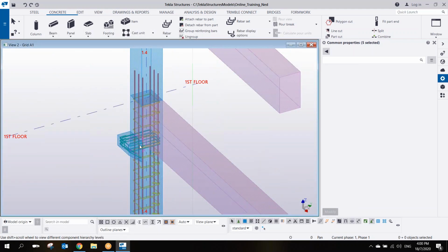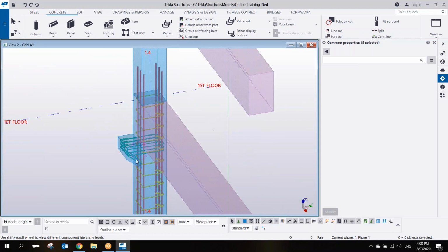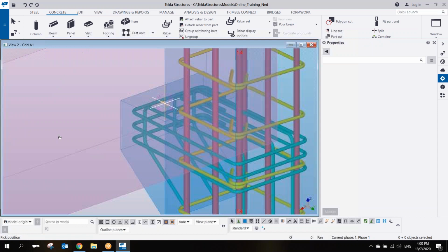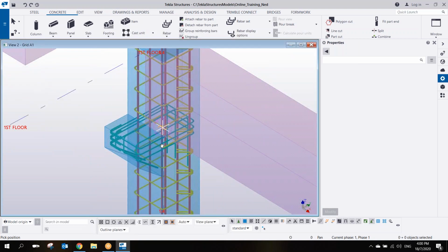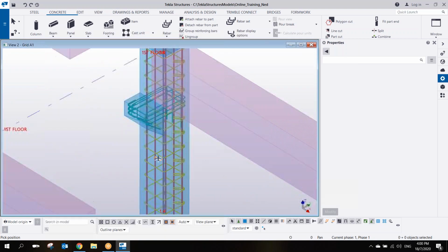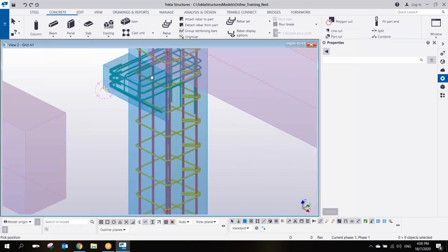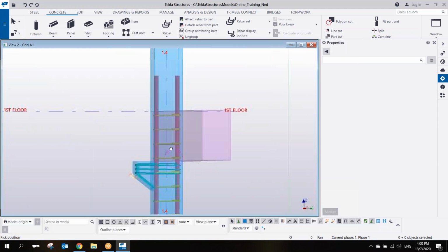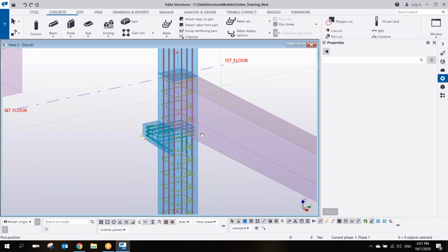If you also feel that when I rotate, it rotates to the other side, you can always press Control R and then click so that you can rotate to the position where you want to rotate. Don't use the Control and then middle button of mouse. You can press Control R and then click the position where you want to rotate. Because sometimes when you use the controller, it goes the other way. All right, let me know once you're done, and then we are going to continue again to another sample.